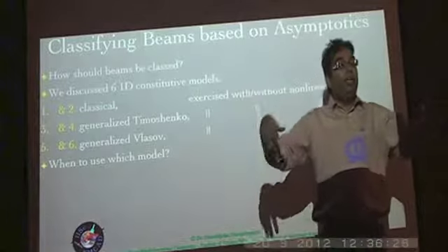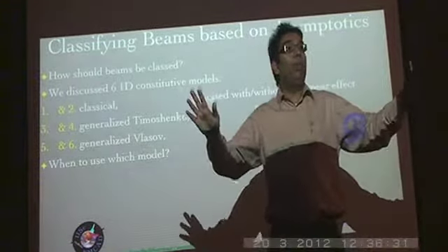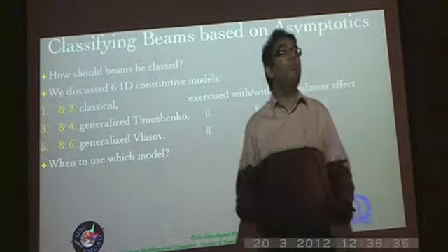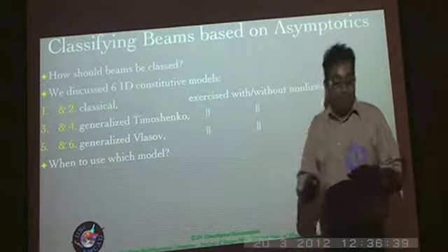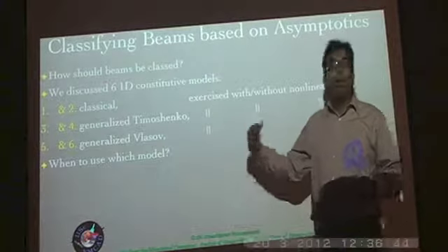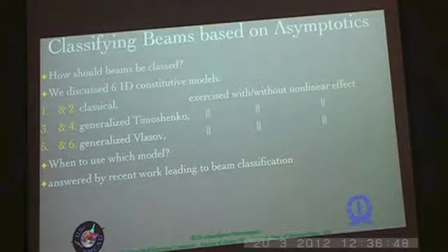But in general, those are the only two small parameters that we really need for a beam. But when we have special cases like thin-walled open section beams or thin strip-like beams, then you have an additional parameter coming from the thickness to width ratio, and depending on that, you might have to choose different models, and that again follows purely from the mathematics.